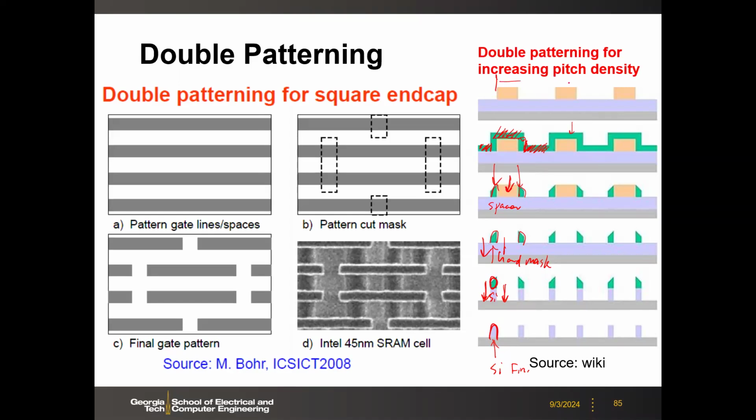Your photolithography defines this notch pattern, right? And then the green one is by deposition and etch. That is more controllable in terms of nanometers, right? So you can, let's say, deposit maybe 5 nanometer thick green material, and after that you will have only 5 nanometers in this direction.